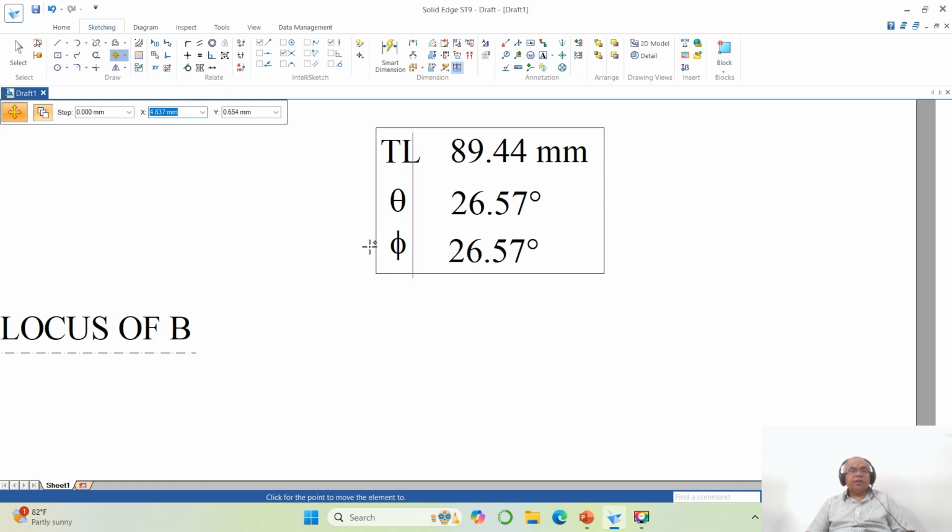Okay, then click to move from. So I don't want to move this line in the y direction, so the displacement is not there. So in y direction it is to be 0, so only it will move in x. So you take this till here, then escape. Then similarly you go to move, then you select this line, then move from somewhere. So there is no y displacement, so its displacement should be 0. Then only it can move in y. So since copy command is there, it retains the old line and also the new line.